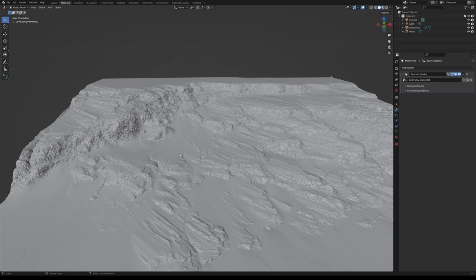And if you're just wanting to use height map terrain for a background and you don't like those stretched faces, this is a way you can get around that as well. So that's what we're going to be taking a look at next, but hopefully this gives you an easy way to fix up those areas without having to manually delete faces, paint them, or sculpt them.